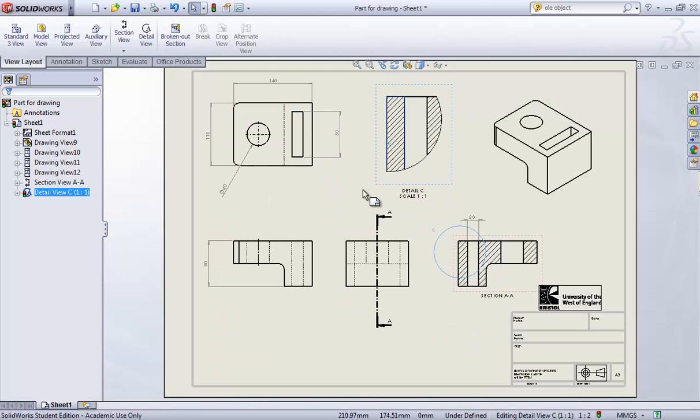I want you guys to research into how to do all of this with assembly drawing. The only change with assembly is you don't detail dimension it, but you may still want to show off the inside, so use the cutting plane and create multiple sectional views. You may want to create detail views, etc., etc.